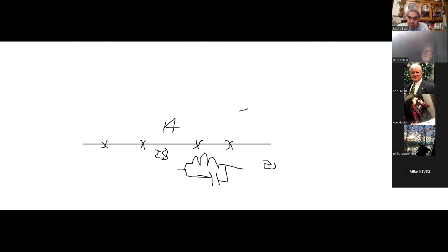Do those megahertz that you just mentioned have any relevance, or is it just random numbers you chose? No, 14 megahertz is the 20 meter amateur radio band. 21 is the 15 meter band, and 28 is the 10 meter band. Things get a little more complicated. There are a couple other bands that the FCC gave us. It's 18 megahertz and 24 megahertz.